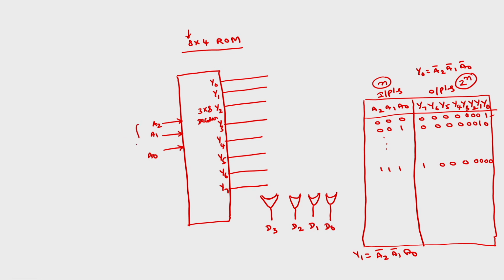These are address lines, these are data lines. So any memory will have some address lines and some data lines. Similarly the microprocessor also has some address lines and data lines. So in order to interface, we have to basically connect the address lines and data lines together, and we have to select that particular memory using some chip select signal. Data lines are the data bus.